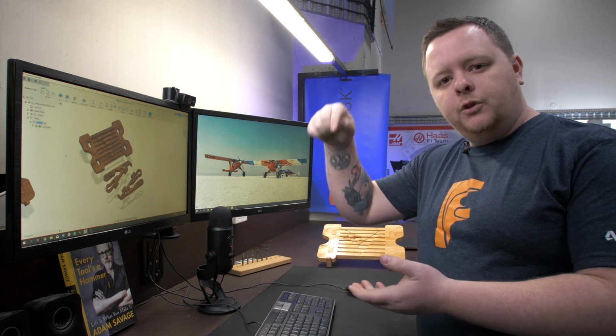So the next toolpath that we're going to do is we're going to do a 2D contour to cut these parts out. I'm going to do two 2D contours. The first one is it's going to leave a little bit of stock and it's going to ramp down into the material. The second contour that I'm going to do is going to plunge down and it's going to remove that last little bit, and it's going to get rid of those little witness marks from those multiple depths when I first cut the part out. That's going to gain me a little bit more accuracy on the part.